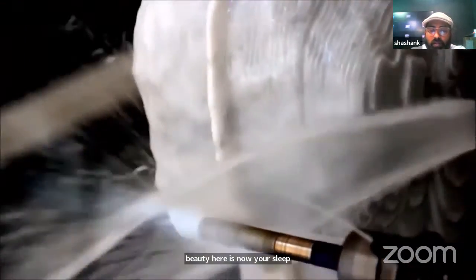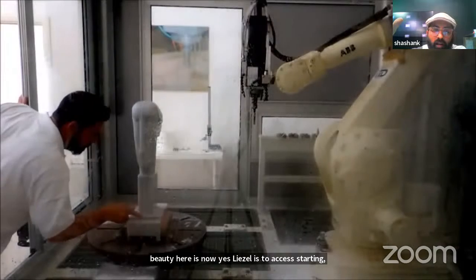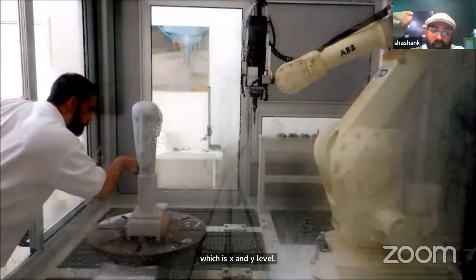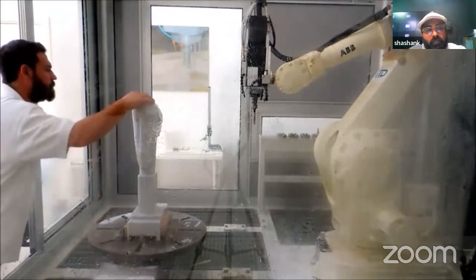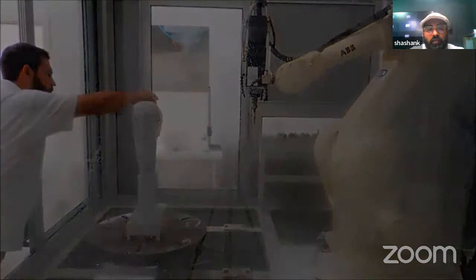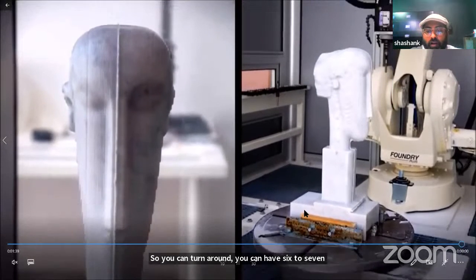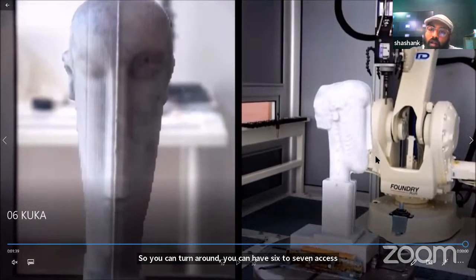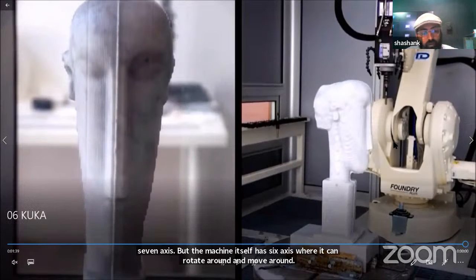The beauty here is now your laser is 2-axis cutting, which is X and Y level. CNC routing is the 3-axis, where your Z axis is also there. With the robotic arm, you have a possibility where you are looking into 6-axis. So you can turn around, you can have 6 to 7 axis. So the base is calculated as a 7-axis, but the machine itself has 6 axes where it can rotate around and move around, finally getting you this as a final output.